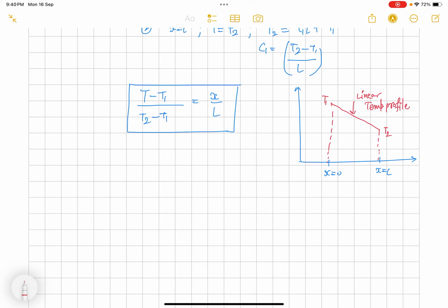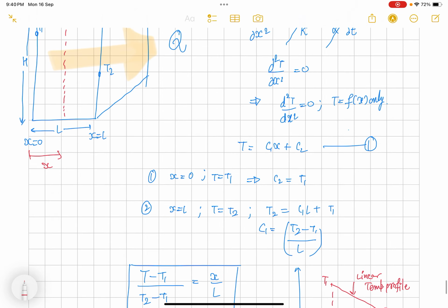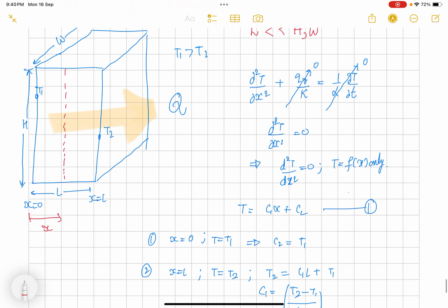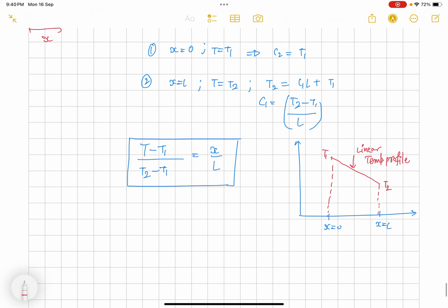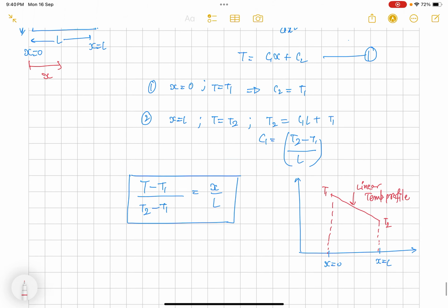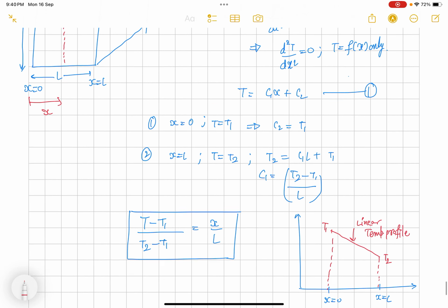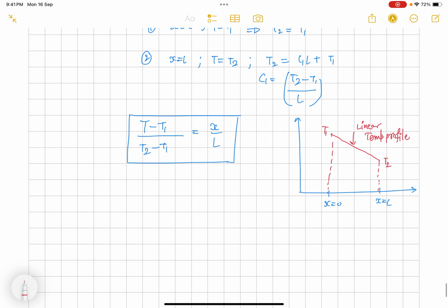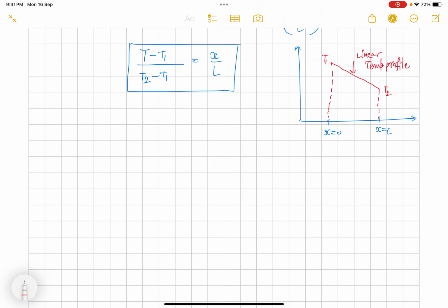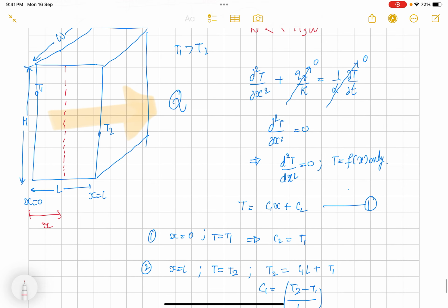So till now we have looked at the temperature distribution inside the infinite plane wall. Now we will see the thermal resistance of the infinite plane wall. If we put this temperature profile in the Fourier law, we can get the heat transfer through the plane wall in watts.